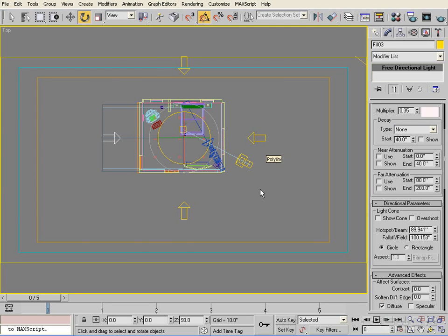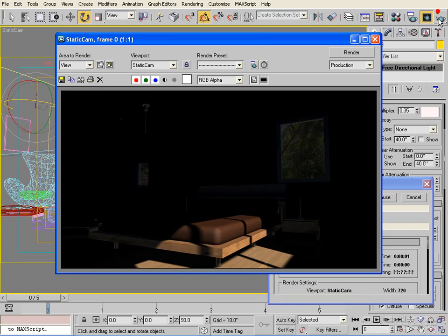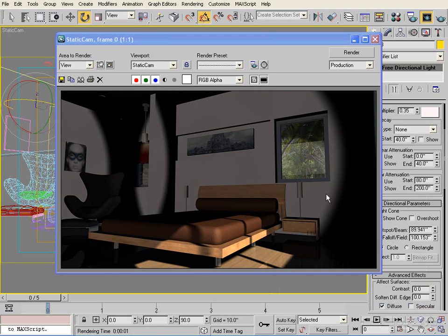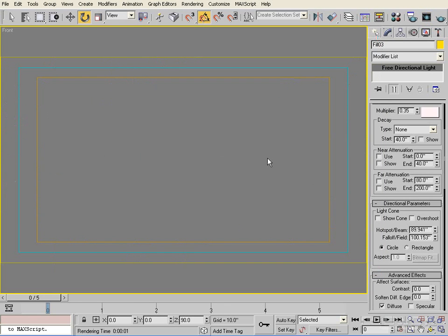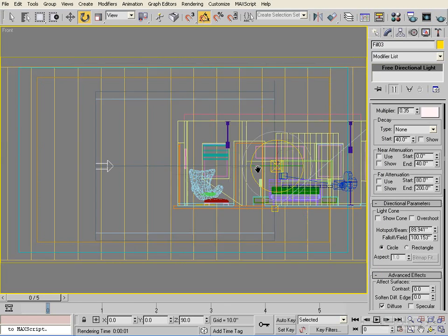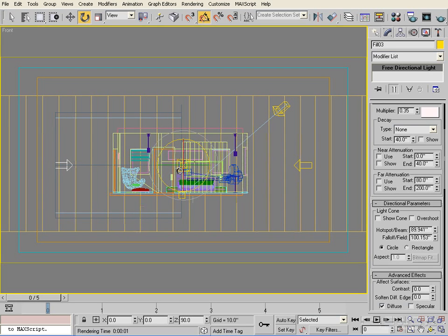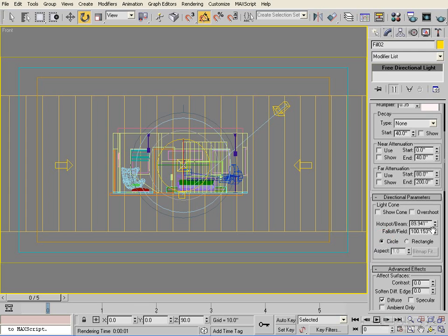We'll just go to a front sort of camera view and just see how they're working. Now you'll see there that our fall off is not working. It's not encompassing the whole scene. So we'll just go back to a front view, and we'll make sure we can select this front fill light here, and we'll go to the fall off, and we can wind it up here similar to our light view tools that we had down the bottom.